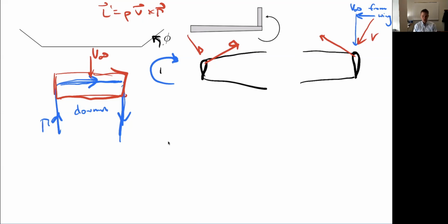All right, so again, if it's flat, cosine of 0 is just 1, it's unchanged. The induced drag equation is the same, except instead of downwash, we use normal wash. Remember, normal wash is the induced velocity. Actually, I'm not sure that we've talked about that yet. We will be soon. So the general case is that downwash for a planar wing, that's what matters. But for induced drag, what matters in general is not the velocity downward, but actually perpendicular or normal to the surface. So in this case, it would look that way. So we'll just write it like that.